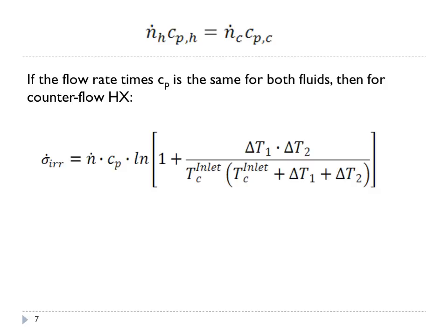The next thing to point out: let's say the temperature cold on the inlet is closer to room temperature. The exergy destruction increases with delta T1, meaning the greater the driving force, the greater the exergy destruction. It's also going to increase with delta T2, where delta T2 can be seen as the total amount of energy transferred.